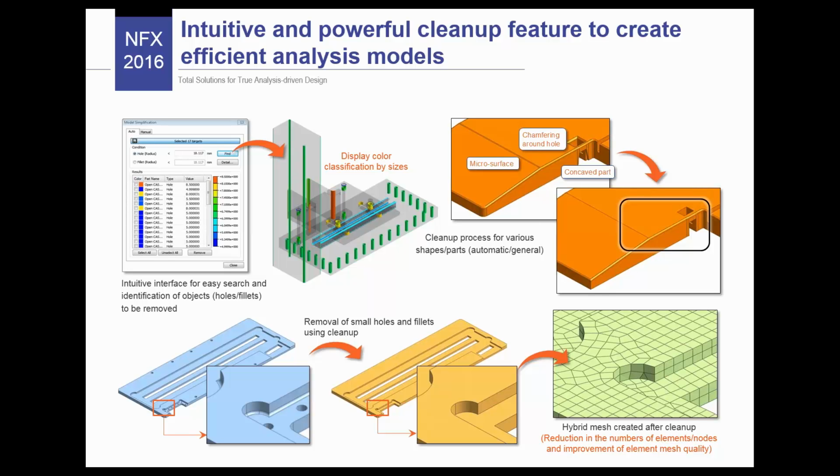It's not always the case, but a lot of the time you have a lot of small holes which are actually aesthetic, let's say, but not really impacting the stiffness of the model. And all these things create difficulty for the simulation because the meshing will need to be smaller in some areas, and then you will introduce more mesh, so what a lot of people want to do is just simplify all that.